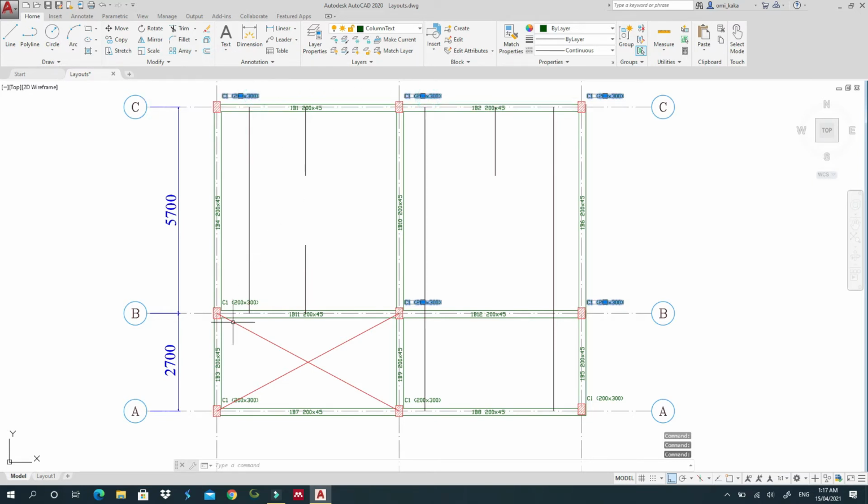We don't need this in the slab reinforcement detail, because there is a separate drawing for this. Okay, so this bar will go from here, and it will take 1/3 of this part and 1/3 of this part. So that means I'll draw it on this side, because this side is long. It should be longer than this side. He will arrange the full bar like this one, but when he gets to this beam, he will cut it and have a small one like this one. But I will just put one and put the dimension. You'll get the point when I'm drawing the dimensions.